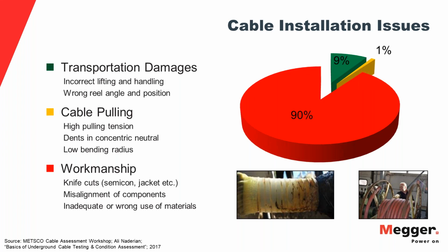Also, when you work in the trenches and a day of work is finished, make sure the exposed ends of the cable are covered, so there's no chance that moisture can get into the cable, which in the long term will also cause accelerated aging. And then you will see this sooner or later during the tan delta testing.